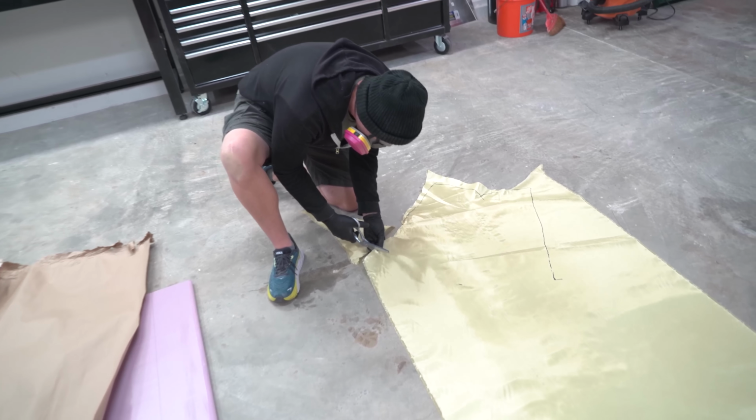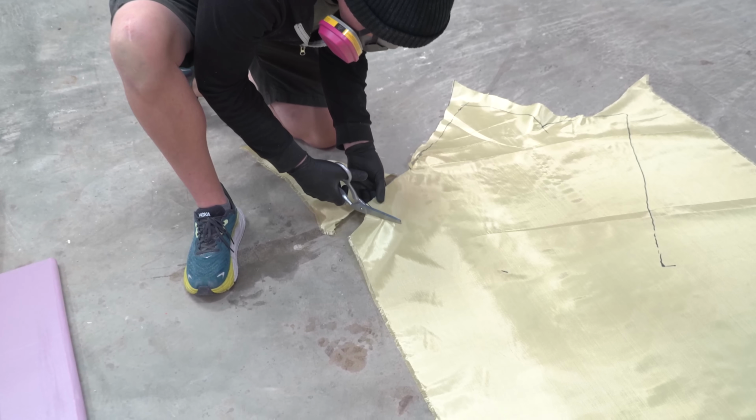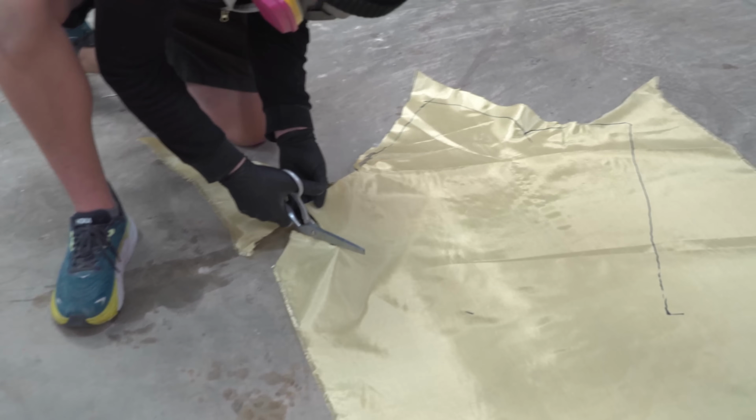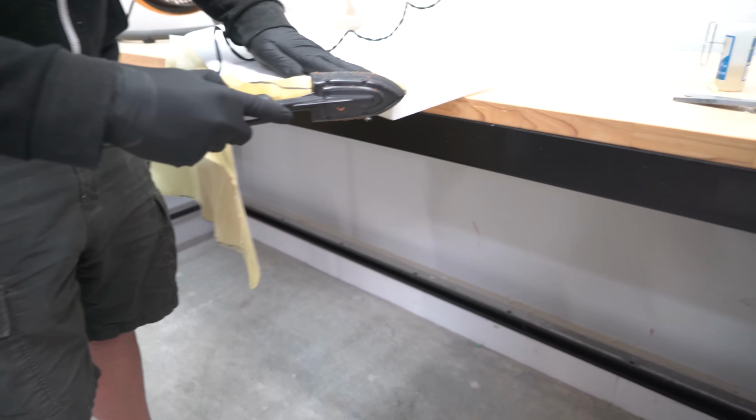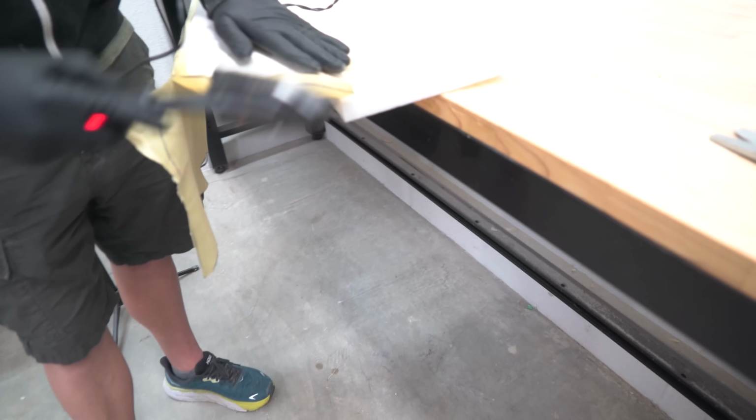1.7 ounce plain weave Kevlar is marked to cover one wing half at a time. The cloth is cut so that the fibers cross the main spar at a 45-degree angle. This gives a lot of torsional strength to the wing. Before that is adhered to the wing, a small piece of Kevlar is applied to the wingtip with contact spray where the main fabric will be split to allow it to conform to the wingtip.